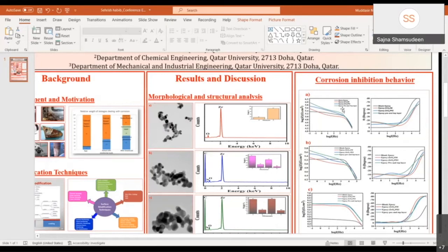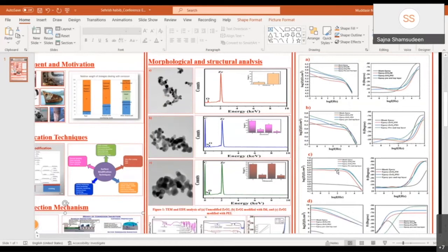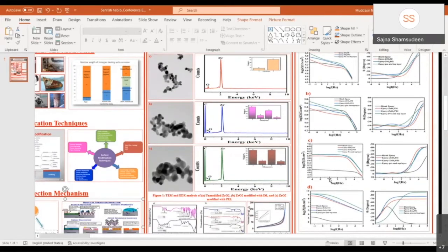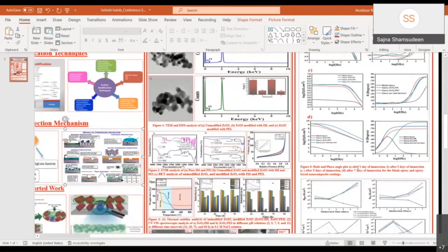When the epoxy coating was loaded with the functional species, we saw that the corrosion inhibition performance increased, and the steel substrate coated with the double layers, that is pre and top layer, has shown high values of impedance with the passage of time. It's proof that the coatings are providing an excellent barrier to the steel substrate from the external environment.